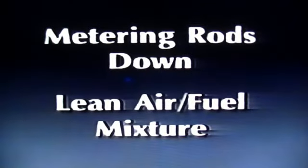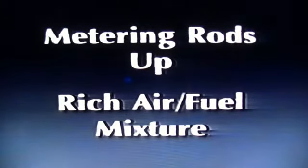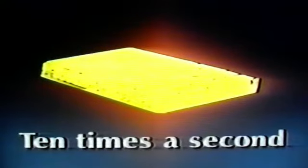The way these work is that when the MC solenoid is energized, it pulls the plunger down against the spring, while the paddle pushes the metering rods down, thus creating a lean air-fuel mixture. When there is no current flowing through the MC solenoid, the spring pushes the plunger back up. The springs do the same to the metering rods, giving us a rich air-fuel mixture in the carburetor. The computer decides how long it will turn the solenoid on, and as we've mentioned before, the ECM makes this decision 10 times a second.